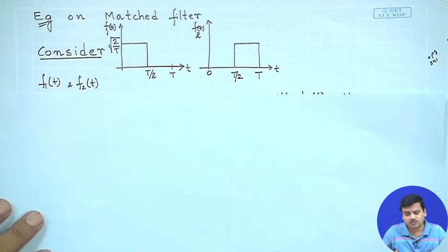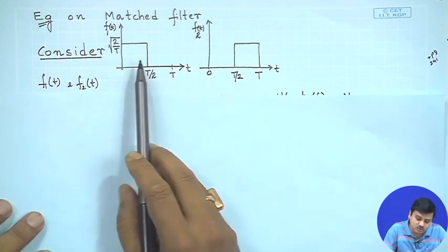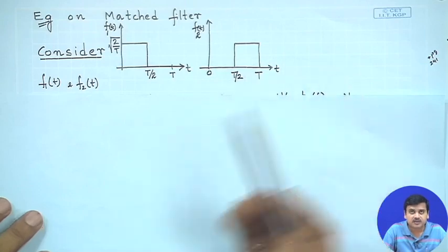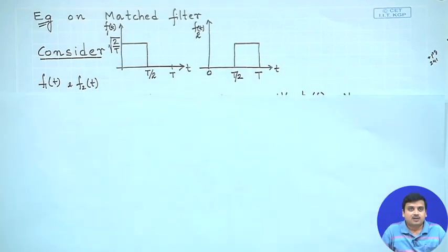So, this would also mean that one could choose these as basis functions, which is a different realization of basis functions. You have seen basis functions in the I and Q domain, that means one that modulates the cosine carrier and one that modulates the sine carrier, but now you are seeing that you could find basis functions in the time domain also. So, it is not new.